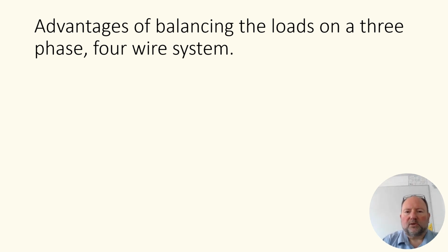There's another question you might be faced with, something to do with the advantages of balancing the loads on a three-phase 4-wire system. So what we're talking about here is a variety of single-phase loads, lighting circuits, power circuits, heaters, cookers, whatever. Across a three-phase 4-wire system, there are some distinct advantages. I'm going to list 2 of them for you immediately,